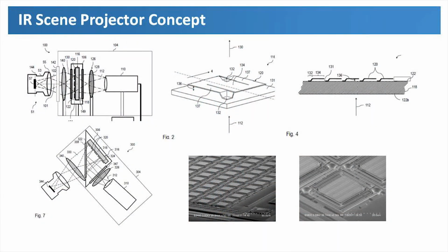I have to say that there is a lot of flexibility in terms of design of the chip. Depending on the application, we can control the following parameters. We can control the number of the pixels, we can control the pitch, and in terms of the numbers, we can even think about 4K type of resolution. In terms of the size of individual pixels, we can vary them typically between 17 micron by 17 micron up to about 35 micron by 35 micron.